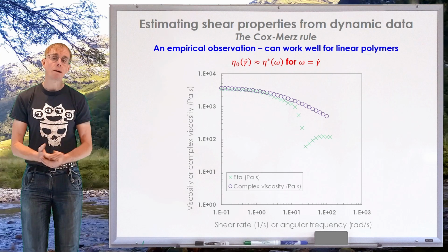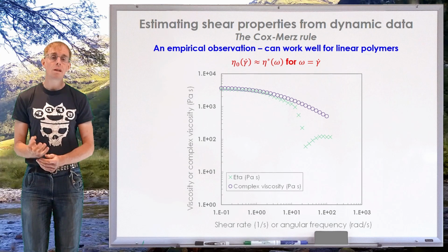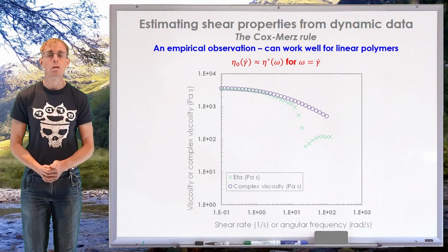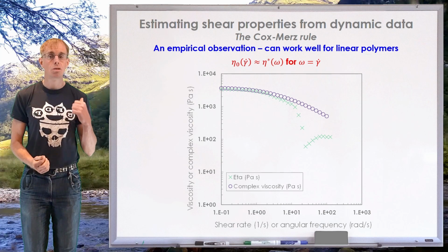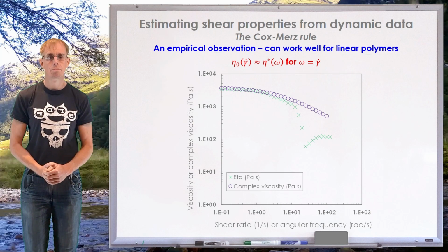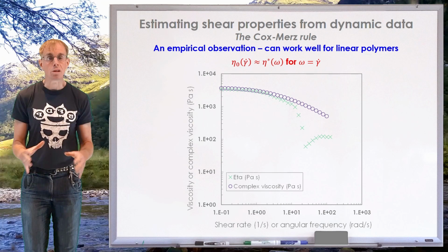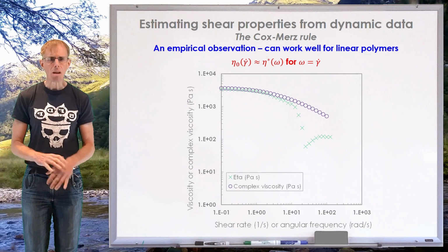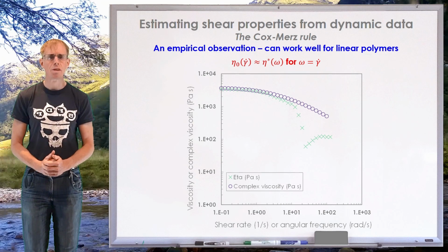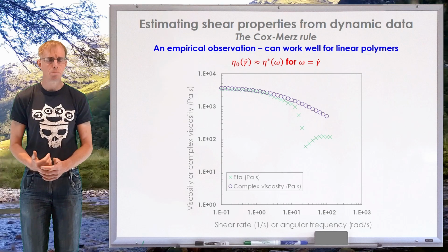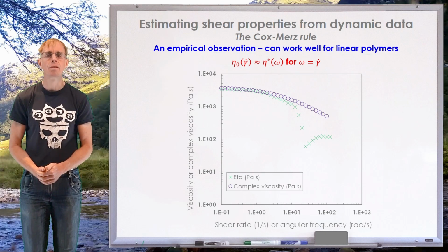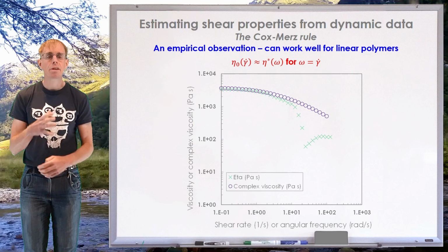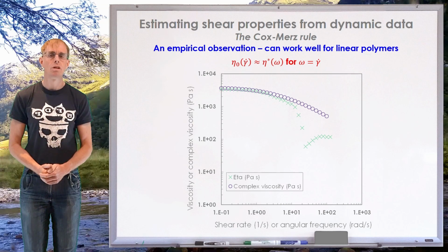And so what this would allow us to do would be to fit a generalized Newtonian model far more readily to our rheology data that we've got. We acknowledge that we're using the Cox-Merz rule to do it. We further acknowledge that we think the material will apply to a Cox-Merz because, for example, it might be linear low-density polythene. It's a linear polymer. But then that gives us a little bit more insight to work with.